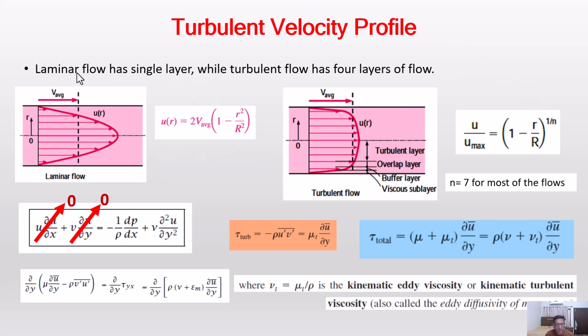And the flow equations are exactly the same, that is the convection term, then the pressure drop and the shear stress term. And as you know, there is no gradient in the fluid envelope flow in the x direction, so this term is 0, and there is no velocity in the v direction, so this term also is 0. So the only terms we are left with are these terms here.